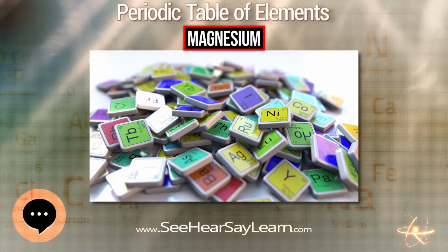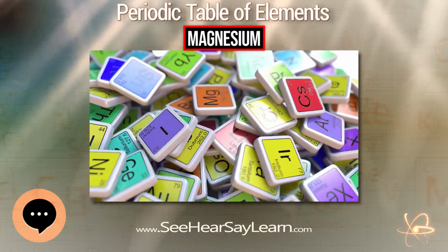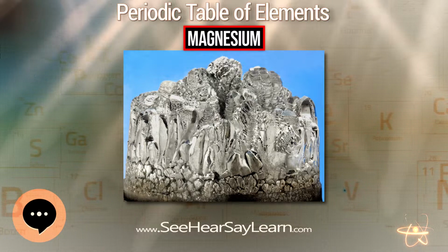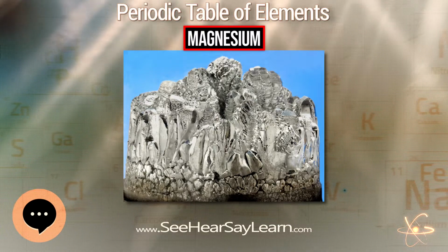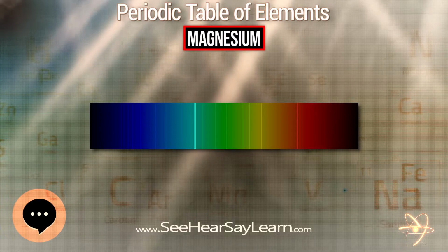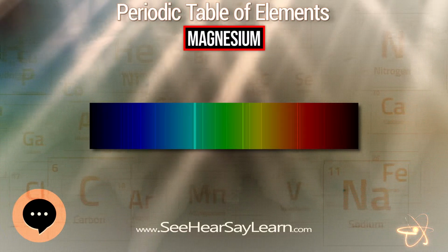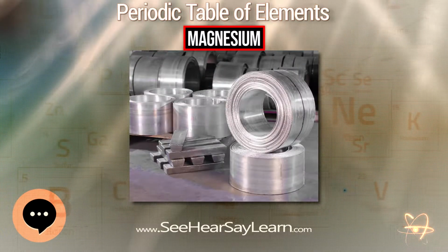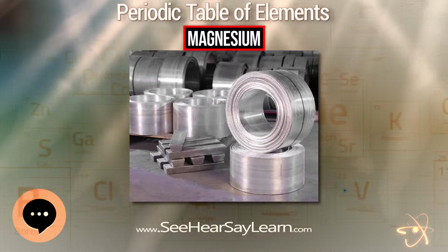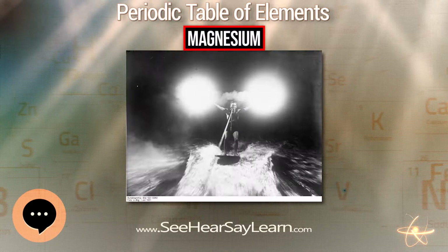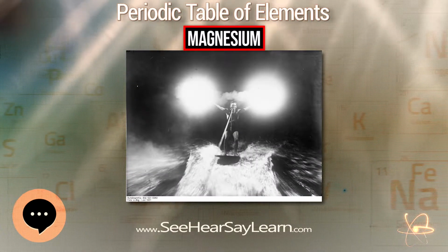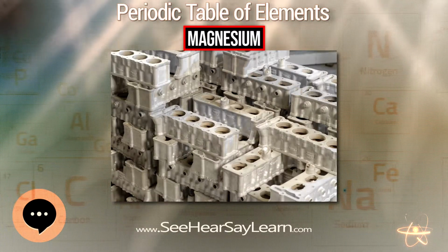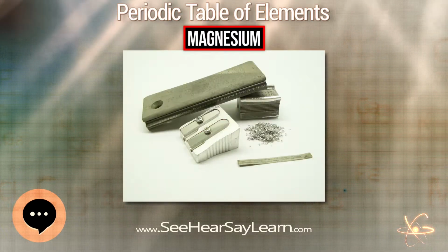Magnesium is used in super-strong, lightweight materials and alloys. For example, when infused with silicon carbide nanoparticles, it has extremely high specific strength. Historically, magnesium was one of the main aerospace construction metals and was used for German military aircraft as early as World War I and extensively for German aircraft in World War II. The Germans coined the name electron for magnesium alloy, a term which is still used today. In the commercial aerospace industry, magnesium was generally restricted to engine-related components, due to fire and corrosion hazards.